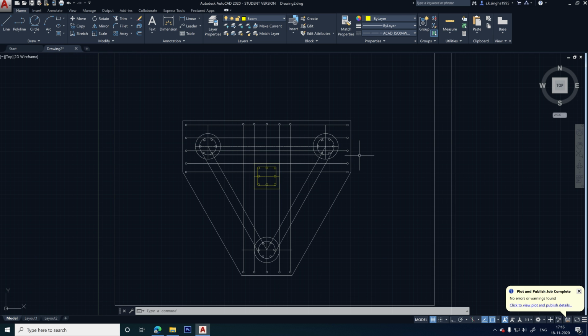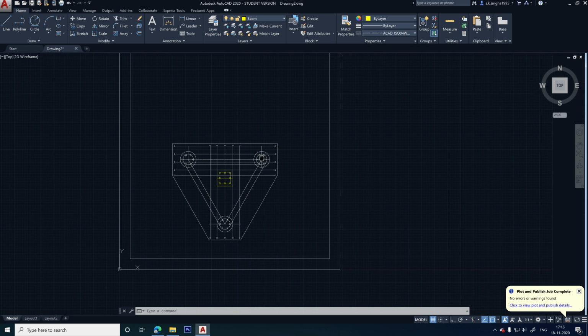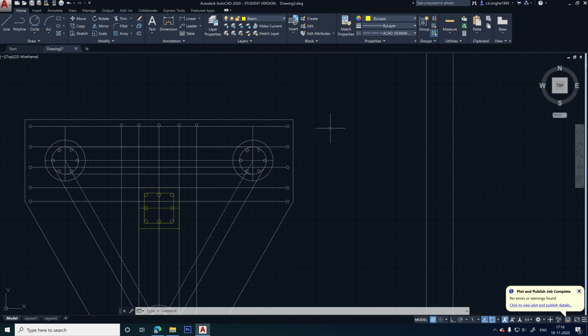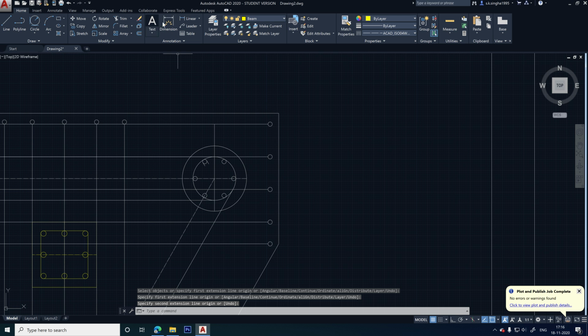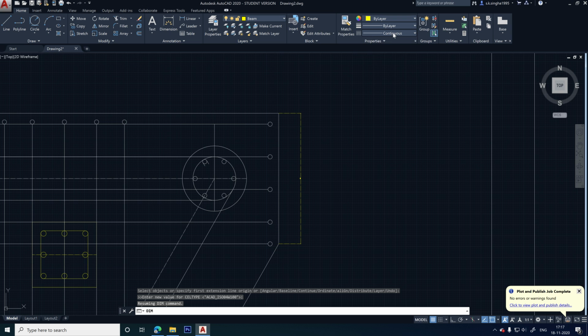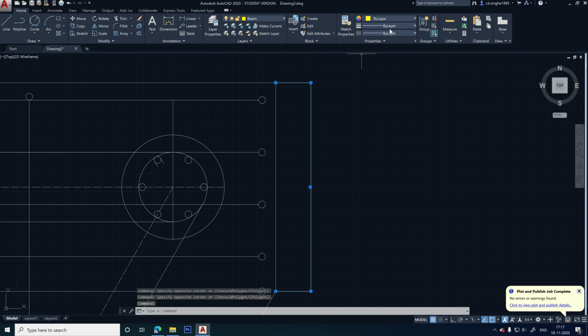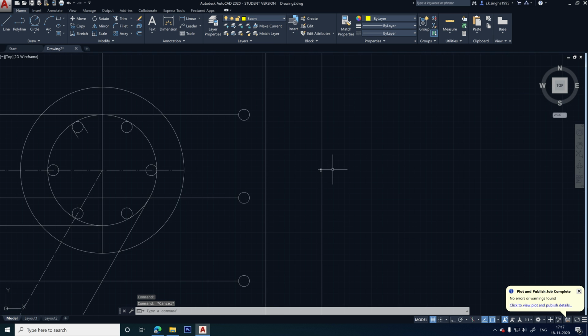Okay, the dimensions and the text are very simple, that you can do. Just simply I have shown how to draw this. The dimension is very simple, you can go here, dimension, you select the places, the corners, change the type of the line to by layer, select this. Change the layer. If you want to make a separate layer for the dimension, that is up to you. Okay, you can see 600.